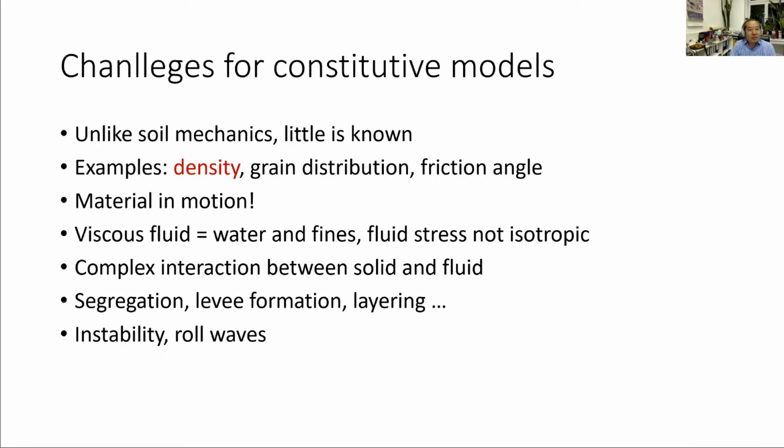The friction angle doesn't help you either, right? Let's have a look at the density. Once the material is in motion, the density is very different, right? The material dilates, with particles flying around. So your density doesn't tell me anything. I could tell you a range depending on the speed. And you see now why it is important to have this kind of mu-I model. Everything depends on the speed: the density, the friction angle. Even the grain distribution curve, you need to consider segregation, and that is not guaranteed. So that is very, very difficult.